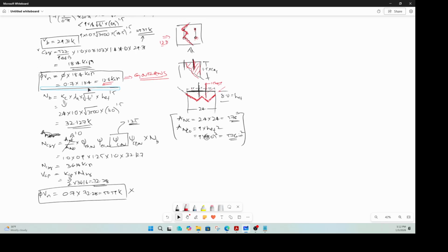Okay, so the problem statement said the pedestal with that grout, and then it is a column. Okay, let's do it here. Here is a pedestal, that's a grout, that is the standoff, and there is a base plate, and here is your column. There are two anchors, and the shear given was Vu was 30, right? So 30 kips is the applied, whereas the resistance is only 12.8.